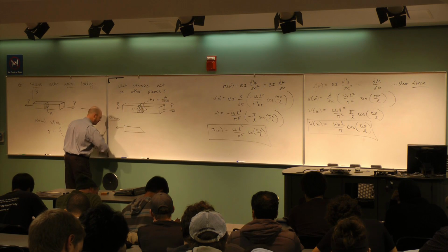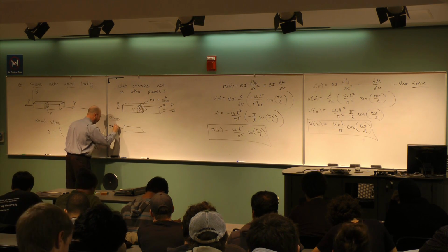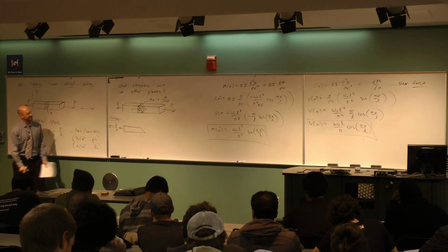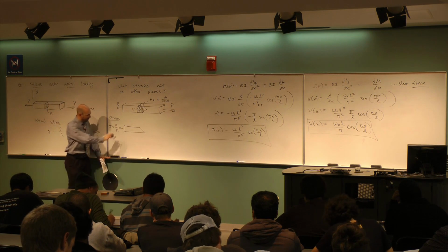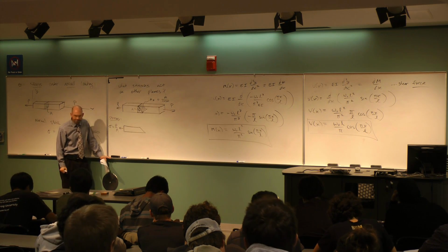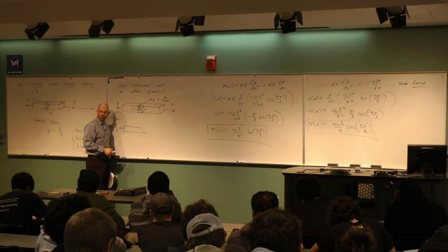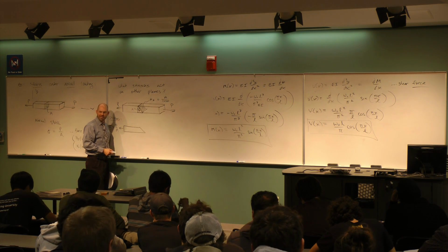This is a stress picture. So in this direction, I've got sigma equals P divided by A. Now keep in mind, this force is going in the horizontal direction. If I come over here on an angle now, and I want to talk about normal stress, normal means perpendicular.